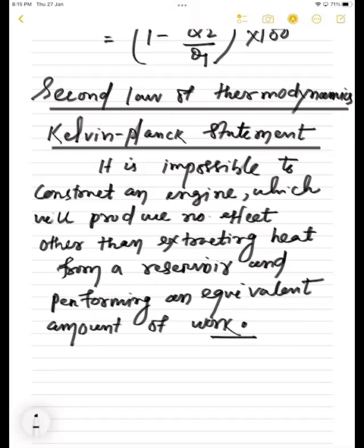What was that actually? Students, this is applicable to a heat engine, right? What does it indicate? It indicates that for the working substance in an operating cycle, we cannot convert all the heat extracted from the source into mechanical work. There will be some heat lost, yes or no? That means we are giving some fuel, and the wheel is moving in the bike. Some heat is also getting transferred, students. Some smoke is getting ejected. Yes or no? That was the Kelvin Planck statement, correct?